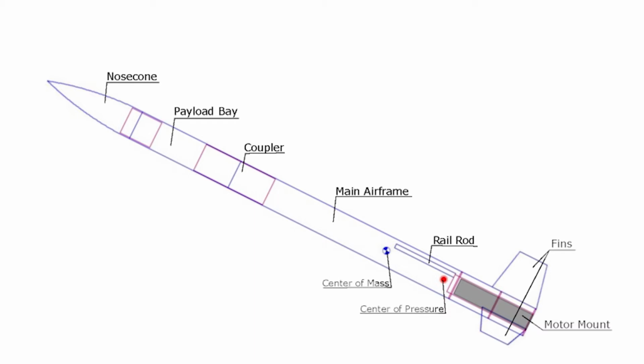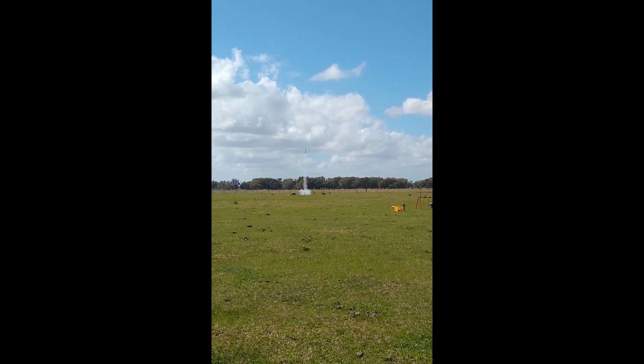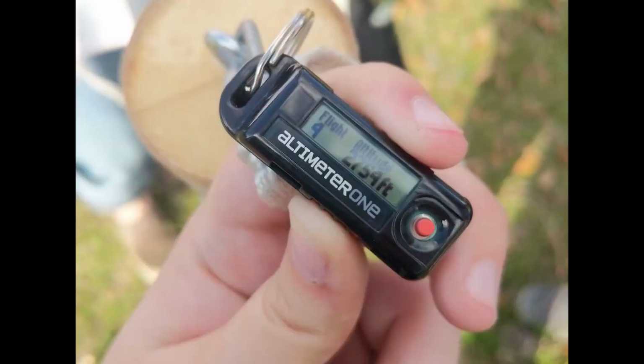Another experiment done with this rocket was actually launching it earlier in the year under the guidance of the Tampa Tripoli Rocket Association. There, the center of pressure and center of mass are computed through a simulation, and while that is also an approximation, it did show that the center of pressure and center of mass for the rocket were in the correct order, and the fact that the rocket flew straight and successfully shows the stability caliber was acceptable.